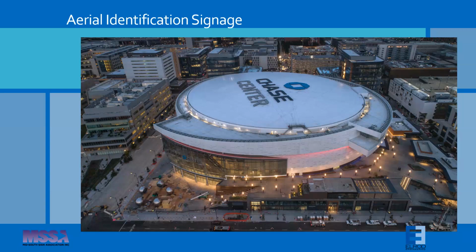The deflection of those sign faces, they were acrylic faces because they're internally illuminated. Normally, when you have channel letters, the face is installed vertically, and you don't really think about how that might deflect. But all of a sudden, you've got a 40-foot long letter and acrylic faces that are sitting within that. They do deflect and sag. How are those going to be supported? If you have internal supports to hold the face up, will that create shadowing effects? How do you physically get the letters up to the center of the roof when the crane won't reach that far? Other things that had to be considered: the framing of the letters was large enough that thermal expansion had to be considered to make sure that you didn't cause problems with the faces contracting and expanding, creating gaps or cracks within the faces themselves. All kinds of fun things as part of this design.